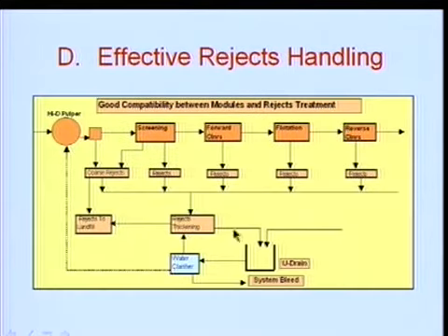In the next system, we do the same thing, but we treat this water by a clarifier, a dissolved air flotation clarifier preferably, and take some system bleed out, throw some water away, and take most of the water back in the system. Here we have done this so that we can remove all the inks and some fillers, some stickies, some waxes, some fiber that was in this stream from the thickening module, and remove them. That improves the system much better, and hence the efficiency of these screens and all these modules will be kept at what they were designed for. And we must take a system bleed, because once you do that, you don't want to close the system in a way that your chemical balance will be upset. So this helps maintain the chemical balance.